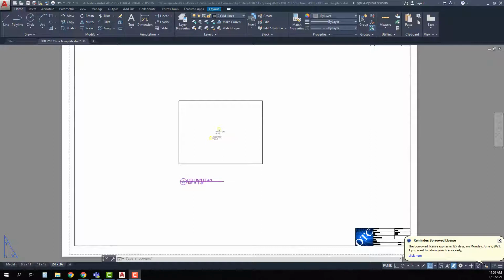We have a concrete slab that doesn't really tell us what that dimension is, so we're going to have to figure that out. If I look at the notes at the bottom, it says outside edge of column to outside edge of slab is 4 inches. Okay, so that's good, but I need to know what the column size is. It goes on to say PEMB to be 30 feet wide by 60 feet long.